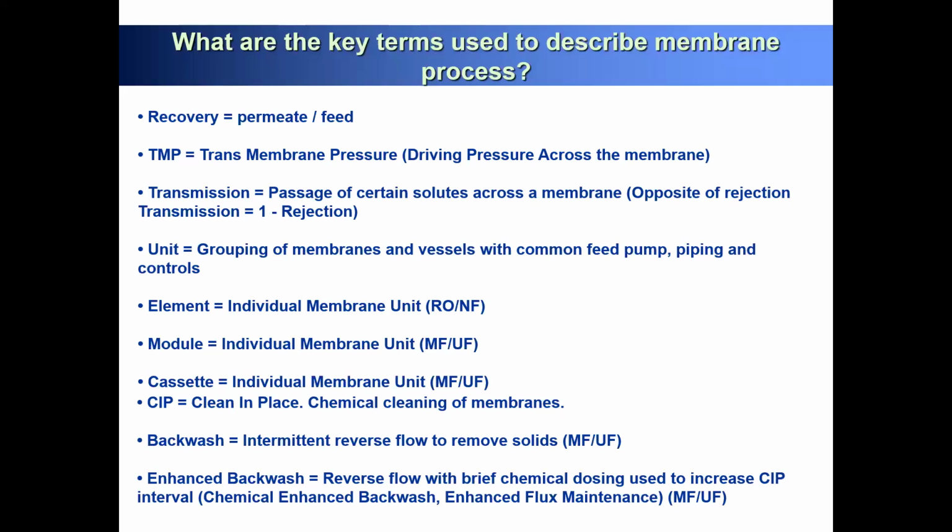Yeah. So you have to design when you have a higher concentration of salt. So 4.5%, your recovery has to be 35%, 40%. For seawater now in Australia, we have 3.5%. So recovery, you can go 45% or 50%.